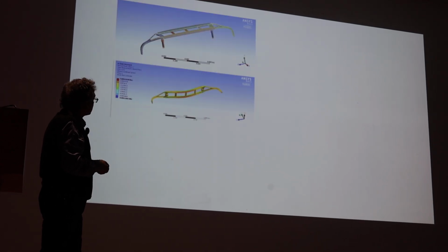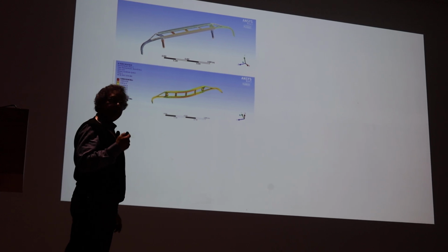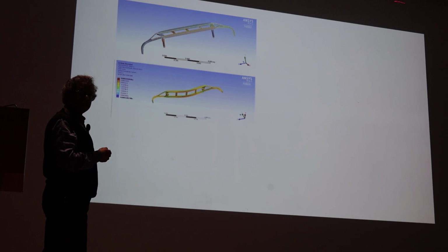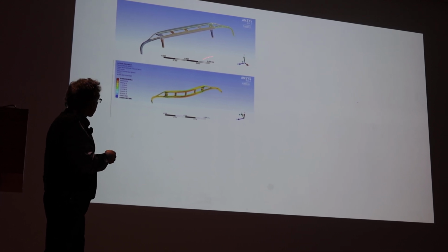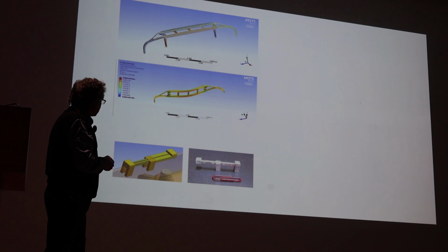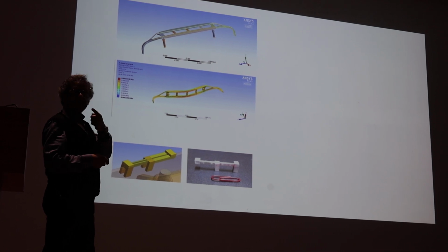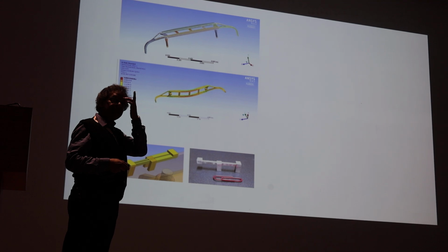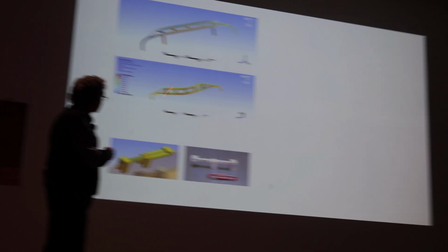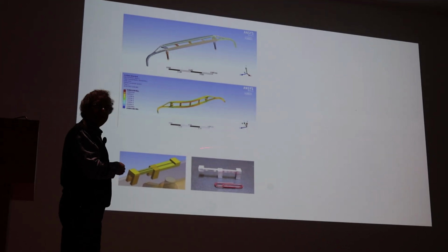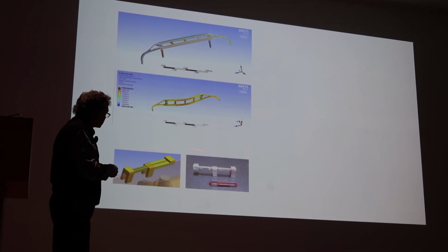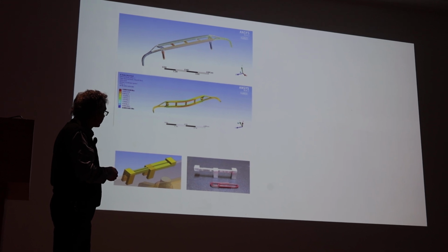I will show you chronologically where we started. It looks very simple, but we started with a pantograph of Indian Railways based on a collaborative effort. Then we studied the whole pantograph and did the modeling. Then we have to protect the sensor, because the fiber optic Bragg filter is inscribed in 125 micron glass fiber. We cannot expect that this glass fiber will be fitted directly to the pantograph, so we need a perfect encapsulation and design. So the design of this housing or package is very important.